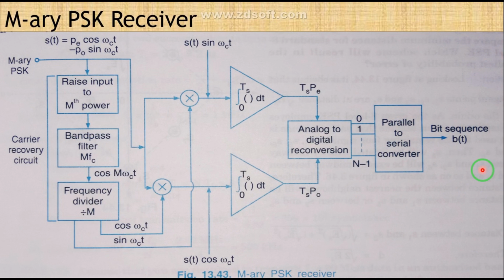Now you can see on the screen the M-ary PSK receiver. It is going to operate on the principle of synchronous demodulation, which we discussed, if you remember, for BPSK and QPSK. And the carrier recovery system, see, this is your carrier recovery circuit.